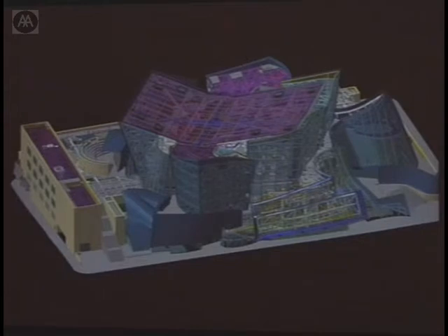So in this particular case, Frank had a specific look he wanted to achieve. With the engineers, there was this very complex steel structure. It looks very complex because it does a lot of bracing for earthquake, and you want the interior wood geometry to be as little affected by the earthquakes as possible, because it's a very, very finely tuned concert hall. They actually tuned the panels acoustically to get the right reverberation time. And so you end up with this black line that you see here. I don't know if you can see this dark blue thing, right?